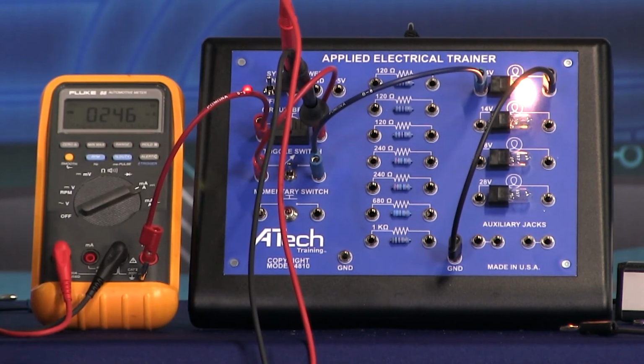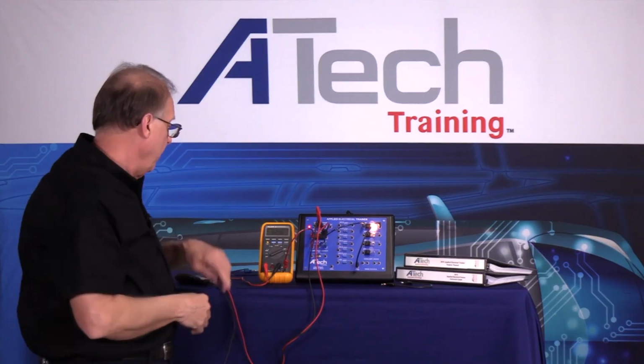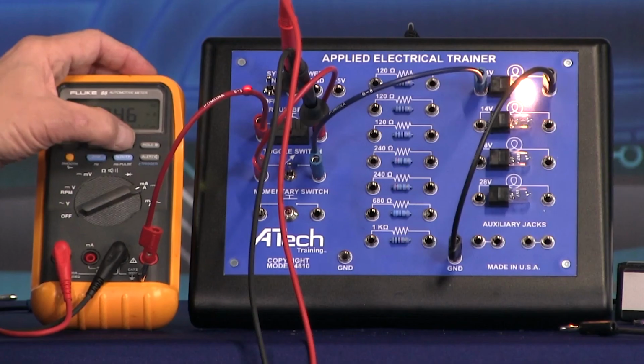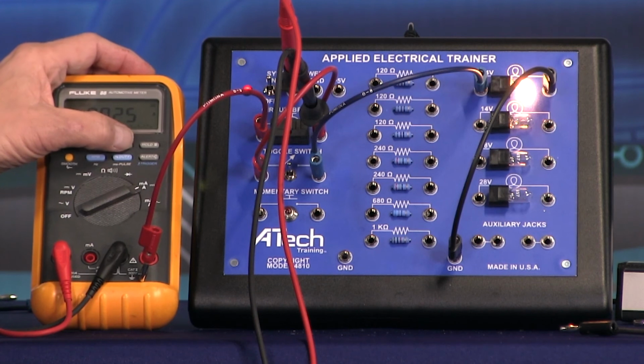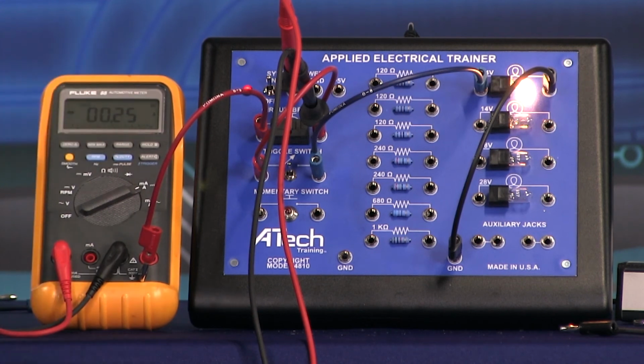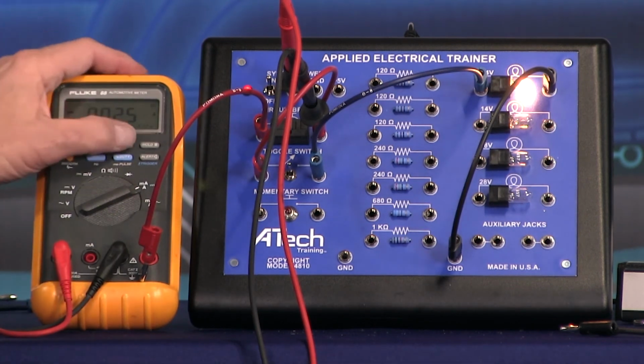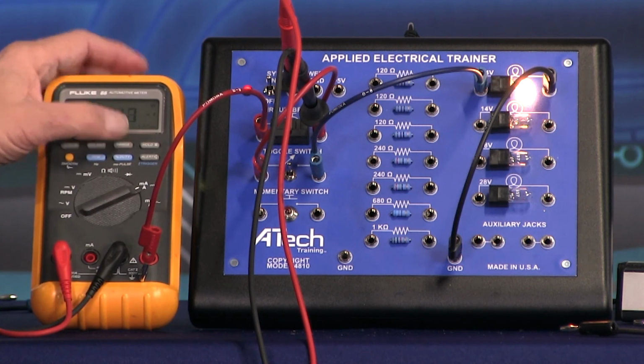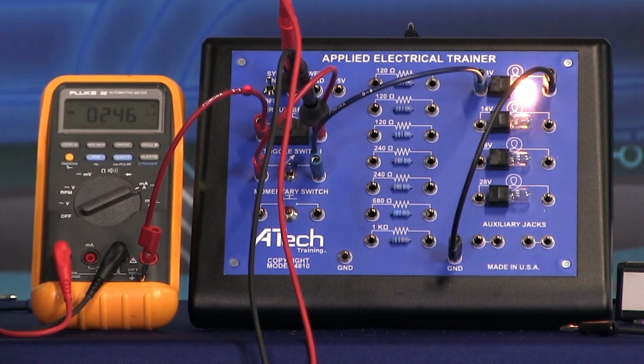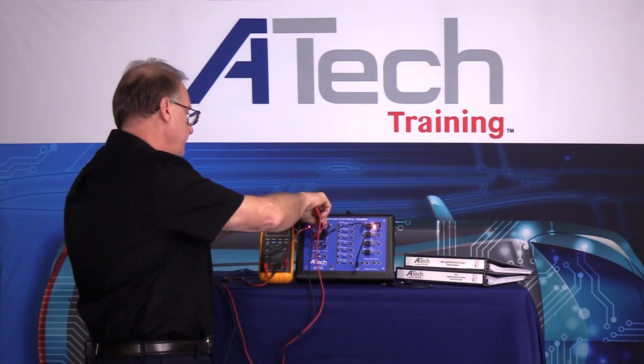If you notice, I got 246 what? 246 milliamps, M for milliamps. So if I was using this, I could actually change my range. Notice it says 250.25 amps. Again, you have to use your circuit the best you can. Sometimes it's a good idea. I got 246 milliamps. All right, that's on the feed side.